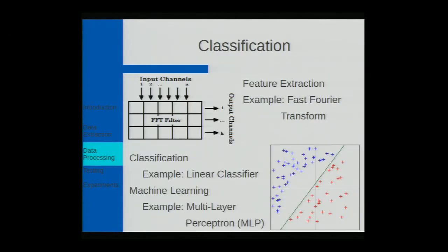And so this is a basic interface I wanted to talk about, so if we use the common average reference, we would average across each node, subtract it from all of them, which would reduce a lot of noise from the interface. These were a couple of modules I wanted to talk about. And if we reduce the noise from all of them, like the EEG headset, for example, the lights in a room, they're at 50 to 60 hertz, depending on your country. They're louder than the brain is to the headset. So we have to subtract that noise.